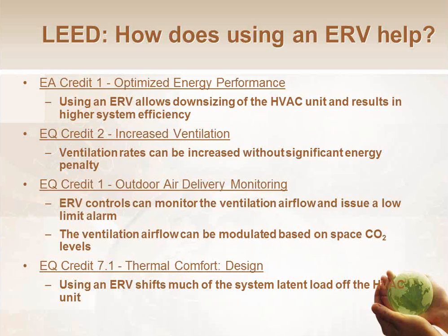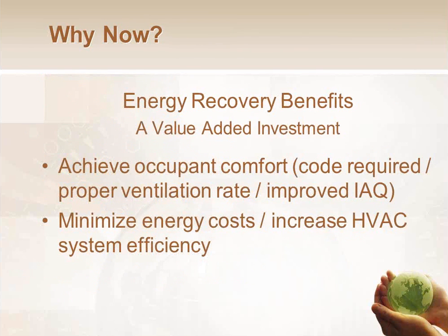You can also, depending on the type of ERV you get, some of them may have built-in airflow monitoring stations, and some of them can be modulated based on CO2 sensors. Either one of those will help you with EQ Credit 1, which is recording data from outdoor air delivery. So you can do that with airflow or CO2 sensors depending on population density. And there's also benefits for dehumidification control that can help you achieve ASHRAE Standard 55, which is EQ Credit 7.1. So there's some benefits there on the LEED side of the equation.